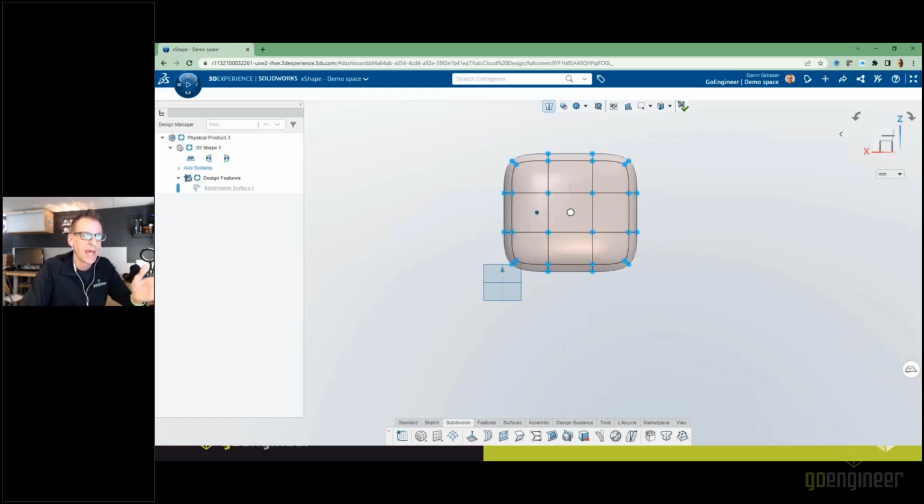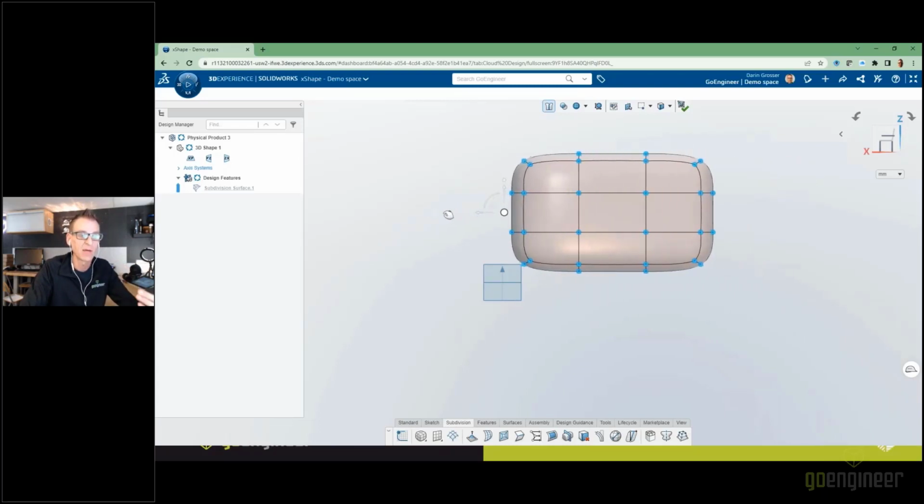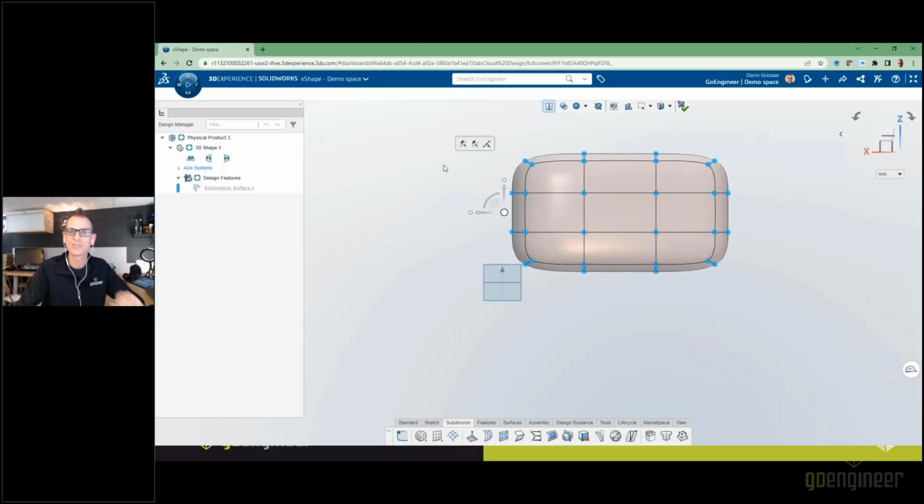Now, like I mentioned, as we use these handles, it's all based on where the robot happens to be. So if I click the robot, you'll see that it actually goes transparent, even tells us down here that the robot is currently detached. And I can use the handle now to move the robot itself, not what the robot has selected. Now, by clicking and reactivating it and putting it into position, the robot is now on the left edge, which means as I scale things, again, it's going to be relative to where that robot sits. So really interesting thing as to the way that works.